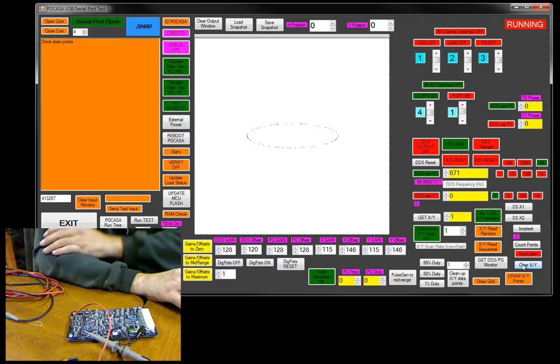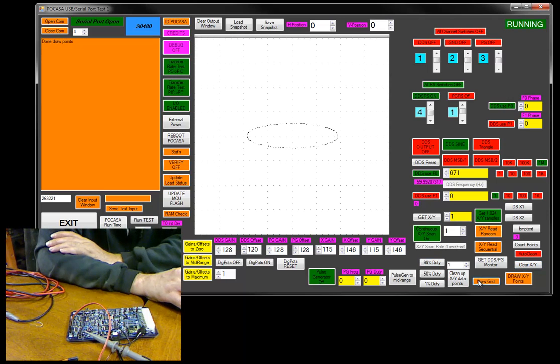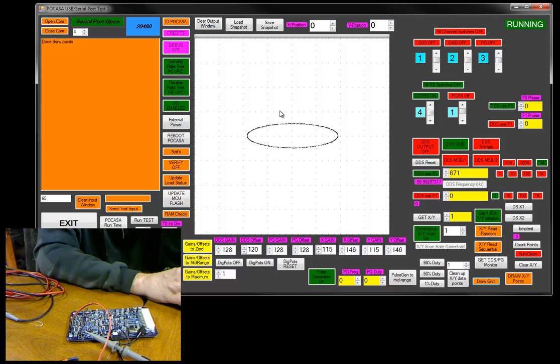There's your capacitive reading. You're getting a phase shift on it, which is causing it to draw a circle. Now the neat thing about this is, if you know the source resistance and you know the frequency, you can calculate capacitance. And you calculate capacitance by figuring out where the perfect 90-degree phase shift is. How do you know where the perfect 90-degree phase shift is? You'll get a perfect circle up here, which is why I got the grid.